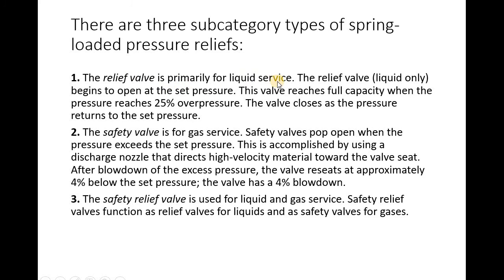A relief valve is primarily for liquid service. The relief valve, liquid only, begins to open at the set pressure. This valve reaches full capacity when the pressure reaches 25% overpressure, which means the pressure over the set pressure. The valve closes as the pressure returns to the set pressure. Easy, easy.